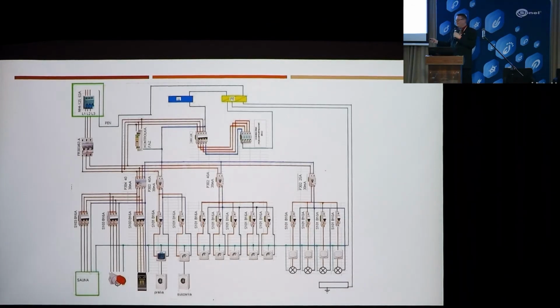If we short the phase conductor here to the neutral conductor, yes, the phase conductor to the neutral conductor, and take the measurement to the PE bus bar. Simple. Of course, this can't be used everywhere. In old unclassified installations, we have two conductors. Well, in those cases, you can't do that kind of thing, but in TN-S or TN-C installations, this kind of measurement can be carried out.